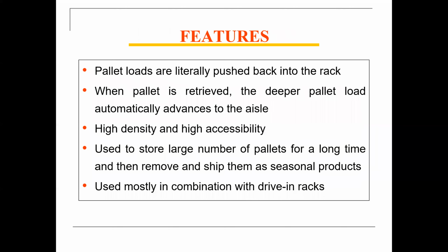Pallet loads are literally pushed back into the rack. When a pallet is retrieved, the deeper pallet load automatically advances to the aisle. High density and high accessibility. It is used to store a large number of pallets for a long time and then remove and ship them as seasonal product. This is used mostly in combination with driving racks.